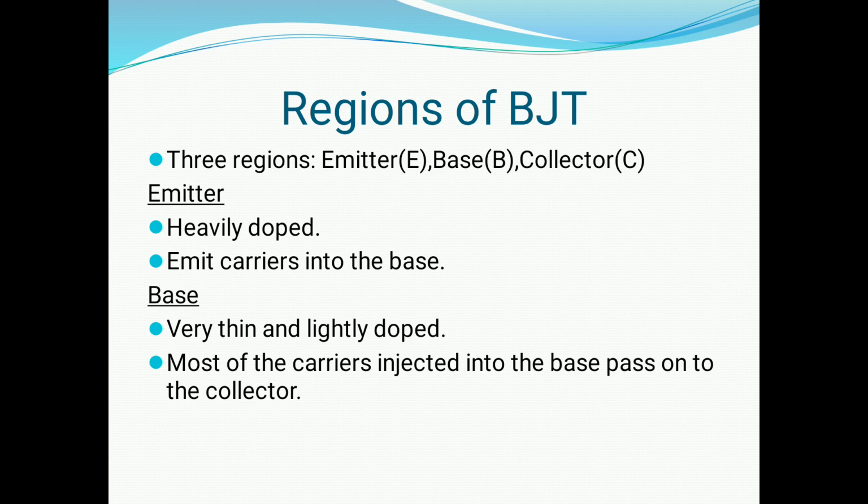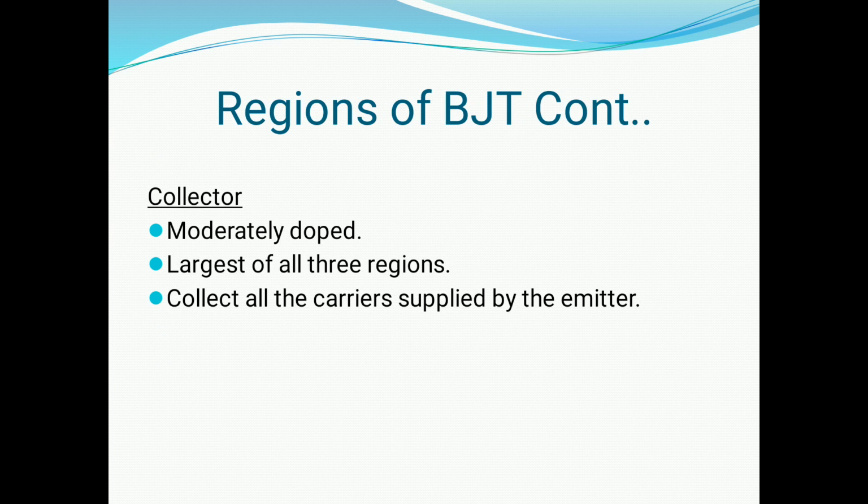Next we have collector region. It is moderately doped. The physical area of collector region is large when compared to emitter and base region. The basic function of collector region is to collect all the charge carriers supplied by the emitter.